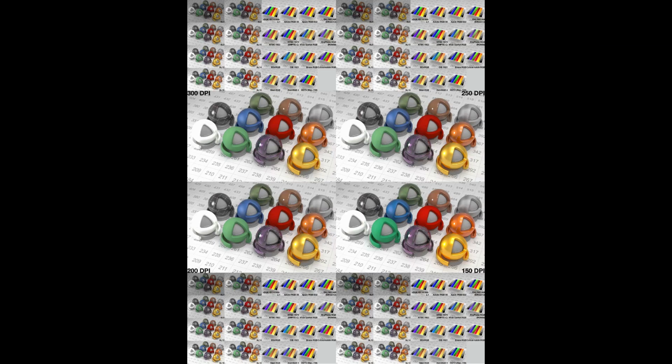And I have done a test print, which should be on your screen now. This test print showed me and others in my class that from a distance of over a meter, you can get away with 150 DPI with ease. The extra complication on top of that is that this also changed the sampling level required in order to make the image appear clean. This is what the test print was designed to show: exactly the same scene, but rendered to different SLs and with different DPIs, and then printed out on a certain type of paper.